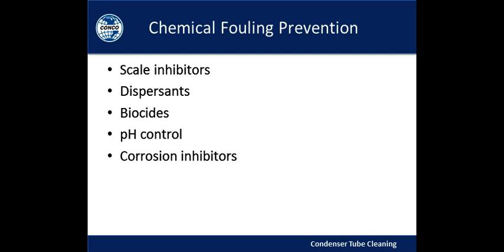Now today we will specifically address mechanical cleaning, but I do have to mention some things about the prevention of fouling through appropriate water treatment. I'm sure that each of you have experience in making selections on water treatment conditioning. And perhaps scale inhibitors or dispersants are being used. You may have tried some very clever pH control techniques to reduce fouling in the condenser.